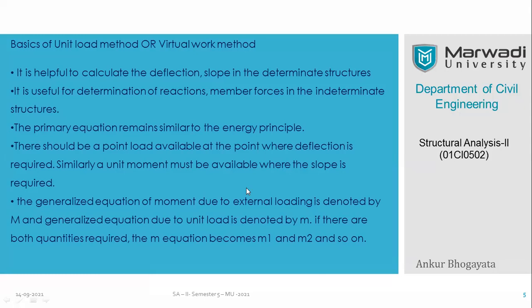Basics of the unit load method or the virtual work method. You must know that the unit load method is also known as virtual work, because here we take only a unit value of whatever actions we are considering, either a point load or a moment. There are only two types of unit loads that we are going to utilize. We are not going to use any UDL for unit load. Please remember, you either need to use a point load or a rotation, and you know the reason why, right?